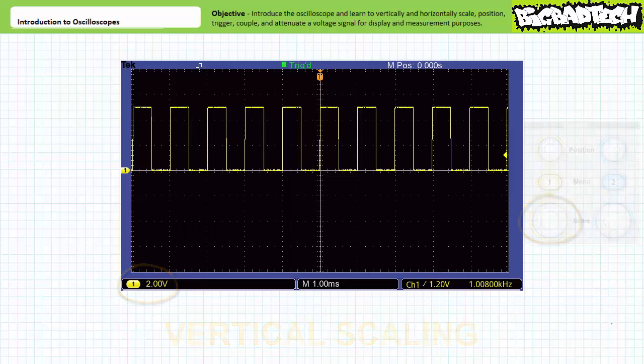Note the pulses appear to increase in magnitude, however this is an illusion only since each vertical division is now worth only 2 volts per division. Given this increased level of vertical magnification of the same 5 volt pulses, each pulse takes up 2.5 divisions at 2 volts per division rather than 1 division at 5 volts per division as previously. Absolutely nothing about the test waveform has changed, only we've zoomed in a little bit.